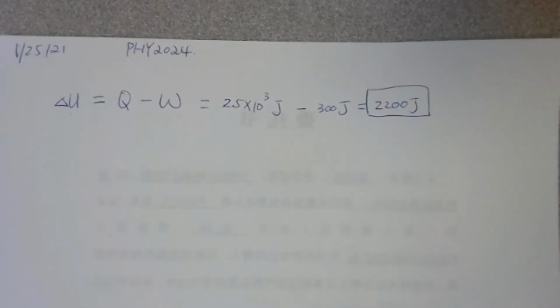So again, in this chapter, when you refer to a system, most of the time that means a gas system. We'll be focusing on the ideal gas or the gas system in this chapter mainly, unless it's specified as another substance. All right, so that will be the internal energy change. So delta U equals Q minus W. Again, keep in mind Q is the net heat change of the system, and W is work done by the system.